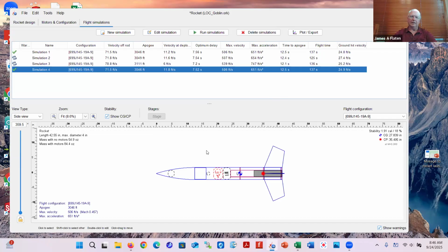Surface finish in particular, it's hard to achieve really high quality surface finishes unless you have very fancy equipment. And that makes a big difference. And so right now I have smooth paint surface finishes and I might be over optimistic. In actuality, I find that OpenRocket and simulating programs in general tend to be slightly over optimistic in how high they think you'll go. Probably that's because you think you will have a higher surface finish than is actually built into the simulator. Okay, that's what I've got.